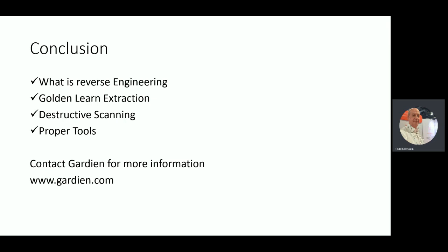The other thing we talked about was destructive scanning, where we do a self-learn again, recommended, and then we actually do the scanning of the board and mill layer by layer, where we expose each layer independently, scan it, and then from there, when we're done, we have our entire set of photo tools that can be created to Gerber, create our drill files, our solder mask, solder paste, and so forth. That can go back into CAM software, generate film layers and all that for you to regenerate the PCB as well.